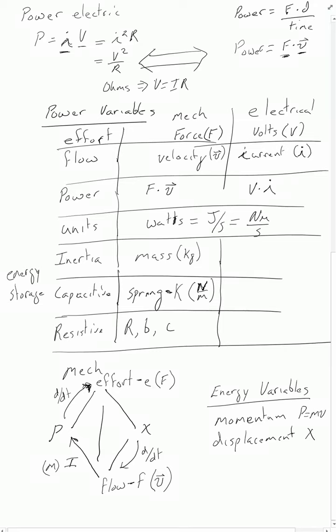And then on the other side up here, we're going to have our spring stiffness, so our K. And so if I take my displacement of the spring times K, I get an effort. And then the resistive element is the connection here. This is just a kind of a graphical representation. The great thing about this is if I know these terms, I can transfer it into the electrical domain, and we will do that in the next video.